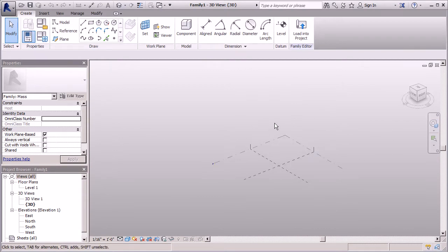So I'll actually be using my shift button and pushing down my wheel to actually do all of my orbiting. And I'll also be using my wheel rolling up and down to scroll in and out. I find these two ways a lot easier than having to constantly look back and think about what view I want to see on my view cube, or constantly having to click to zoom in and out several times using my zoom region.